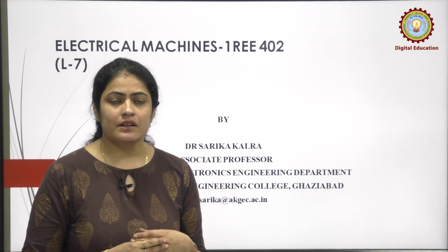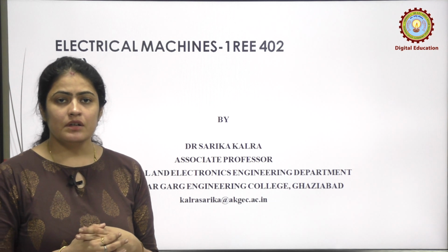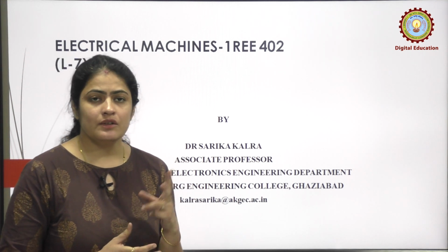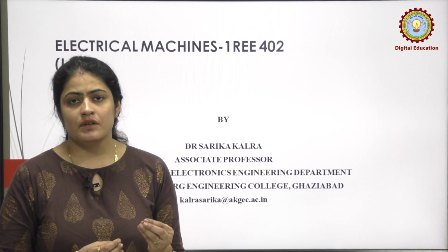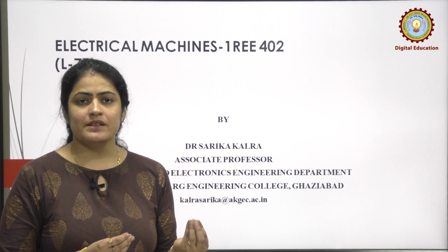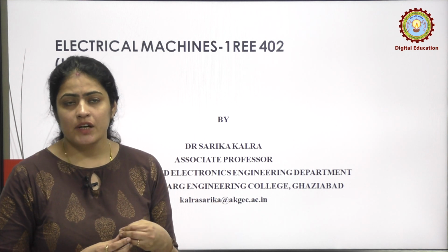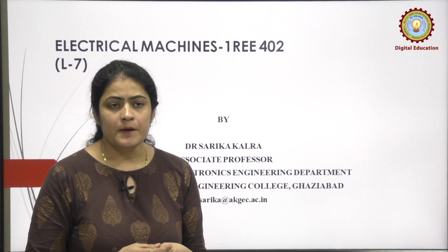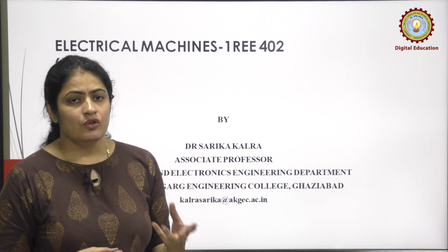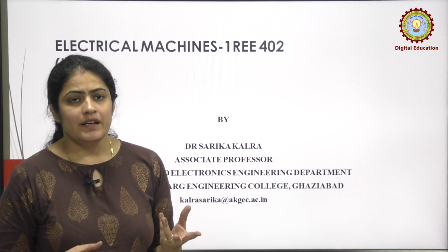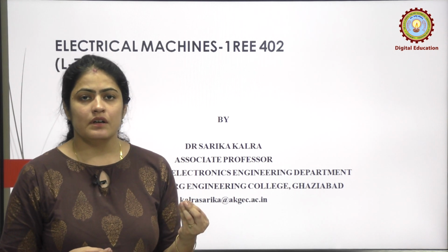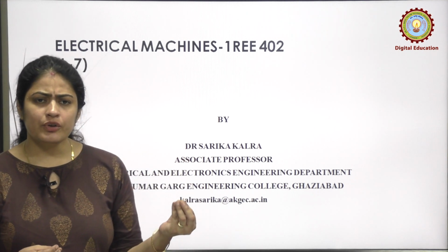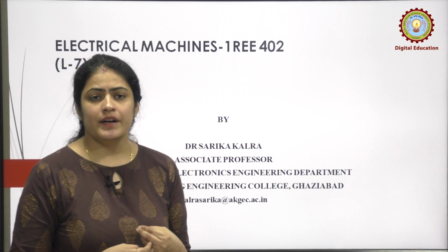Second, we get the power loss, that is the core power loss, because the open circuit test is always at no load. That means the magnetizing current is flowing in the primary only. The primary winding contains only the no load current, that is the exciting current, which in a transformer is 2 to 5% of the rated current.